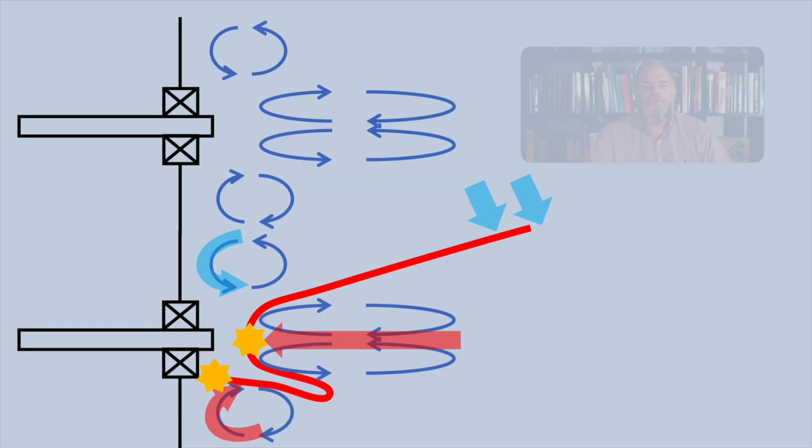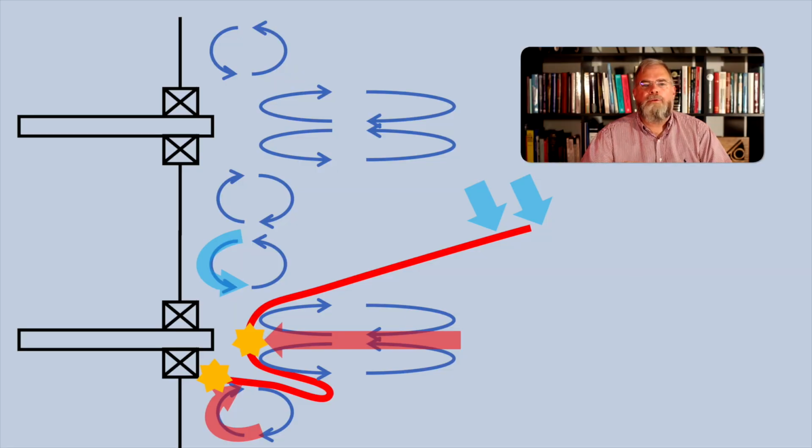And so if there is significant mixing between the burners which are off and the burners which are still on, there is a risk that flame stability could be significantly deteriorated. An additional issue with this is that the slower burning flame on this side of the burner will have more time to mix with the colder air from the burners which are off next to it before the combustion is complete. And this will slow the reaction rates and possibly quench reactions, which will reduce or stop the rate of CO oxidation, contributing to higher CO emissions.